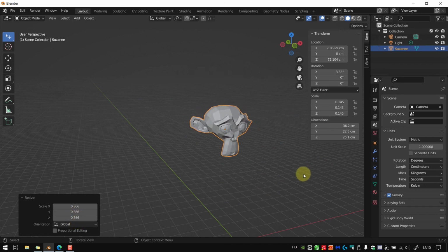Okay, another thing when you are dealing with values is if you are coming in, for example, it's 36 centimeters. But if I'm just typing in 360 millimeters and hit enter, it calculates between units. So if I'm typing 0.36 meters, hit enter, it's 36 centimeters. So it's back and forth. If I'm typing in here 30 centimeters plus 6, hit enter, 36. Okay, so basic arithmetic operations are supported. You can use these. It's quite a good thing.